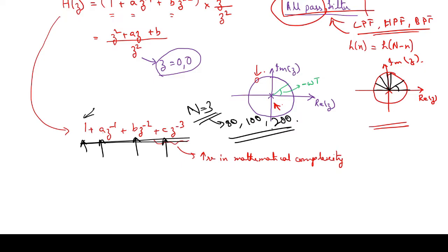So we can be dealing with maybe up to 200 or even a greater number of filter coefficients, which increases the mathematical complexity of our FIR filter calculation. If you consider that you want a similar kind of response with an IIR filter, the order of the filter would be say 3, 4. At the max, we would go up to 10.